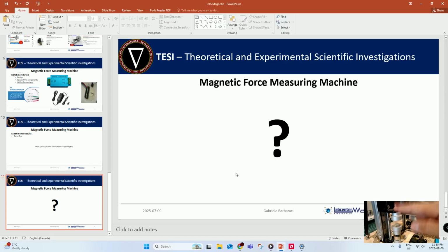This plate has been manufactured as per the drawing shown in the PowerPoint. Another thing is the standoff. Since the shaft of the motor was too long and was colliding with the threaded shaft, I used a 6mm standoff attached to this motor to prevent the head of the motor from colliding with this.